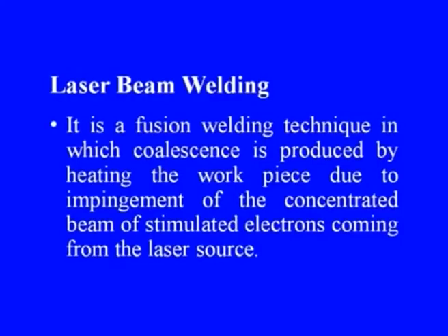Now, let us move on first to the laser beam welding process. As we have indicated already, this is also a thermal based process in which heat will be generated by the application of a laser beam. The coalescence of the surfaces of the material will be produced by heating the workpiece due to the impingement of the concentrated laser beam, which will be coming out from the laser generating device, or what we call the laser source.